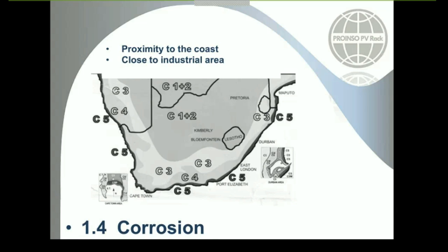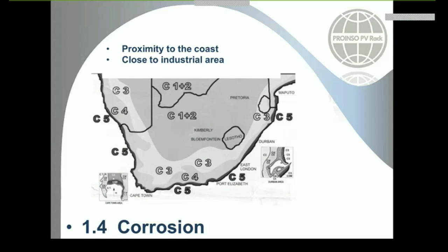However, the anodized coating that we apply is just because of the visual effects that you could see, some rusty areas or something like that, and it gives a little more quality to the product, okay? If you anodize it, those visual effects are not going to appear. It could also give more longevity to the structure: if for aluminium we are talking about 15 years, maybe with the anodized coating we are talking about 20, 25 years, okay?